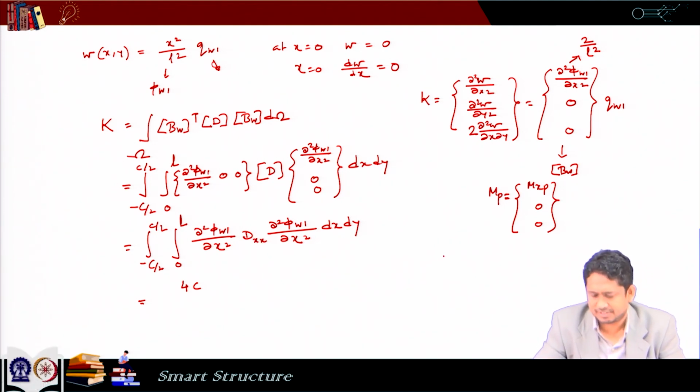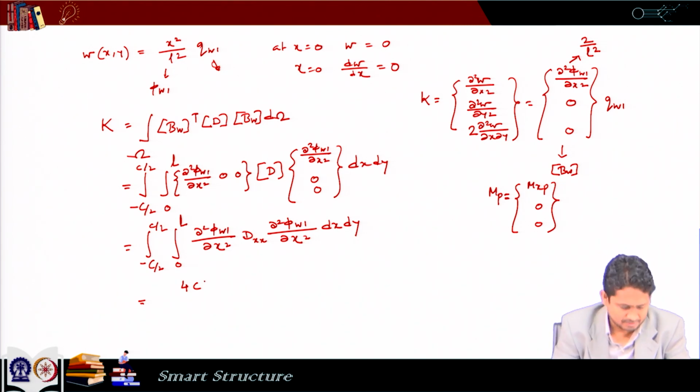So, this D matrix many a times we write it as D11, D12, I mean all these A, B or D matrix, sometimes we write it as A11, A12, A16, or we can write it as DXX, DXY and DXS. So, some books you will find these subscripts to be 1, 2 or 6, and in some of the books you may find it to be X, Y or S, and both are same.